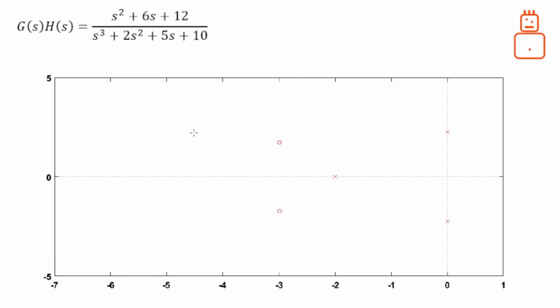Let's do that. Okay, we have this map of the pole zeros. Start with the angle of departures, of arrivals, and the values of the asymptotes. The asymptote here is at 4, so it's out of range. So somewhere here we do have an asymptote with an angle of 180. So this goes to infinity here. Let's put the information of the arrival and departure angles.